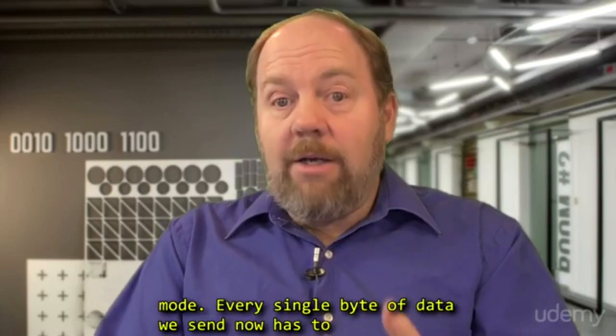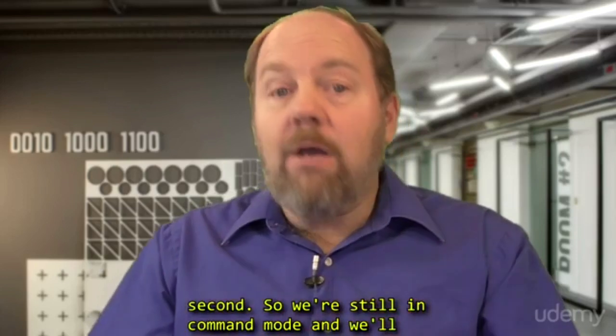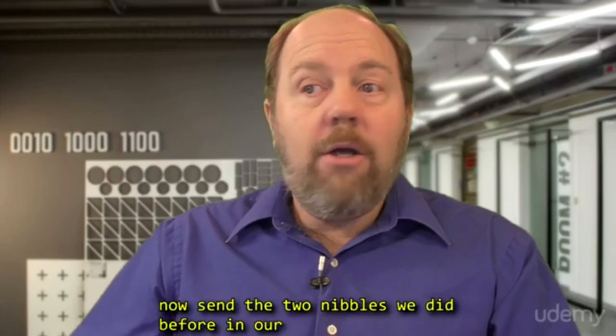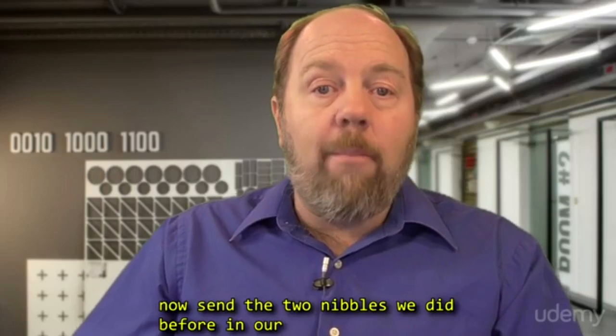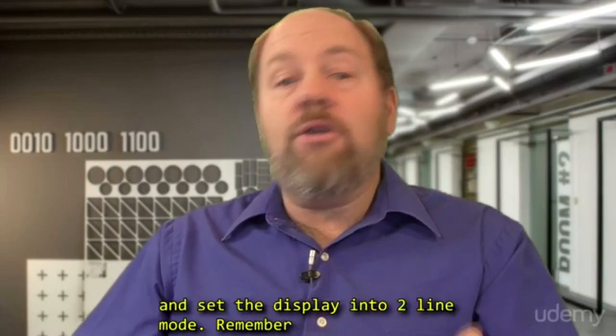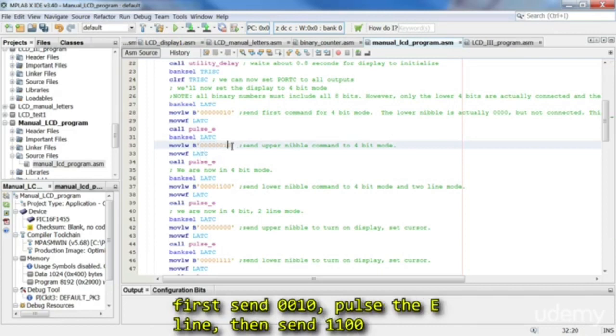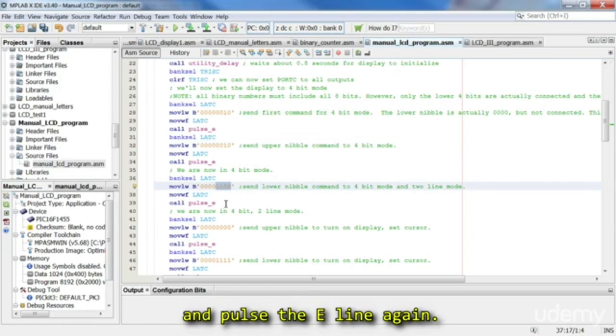Every single bit of data we send now has to go in 2 nibbles. The upper nibble first, lower nibble second. So we're still in command mode, and we'll now send the 2 nibbles we did before in our manual drive circuit. So we leave it in 4-bit mode and set the display to 2-line mode. Now remember, there's nothing connected to these bits. So we first send a 0010, pulse the E line, then send 1100, and then pulse the E line again.